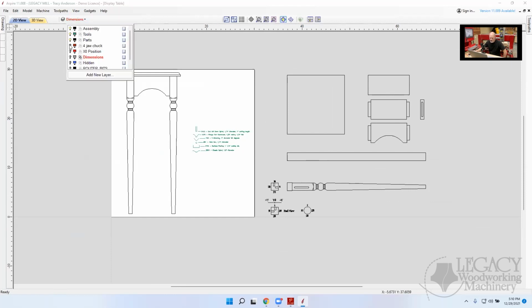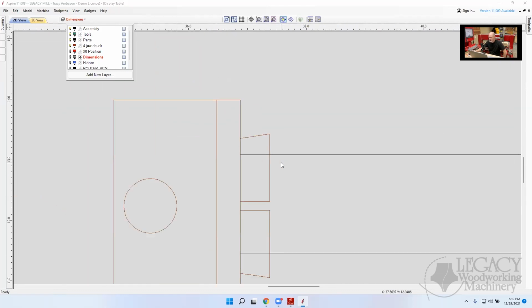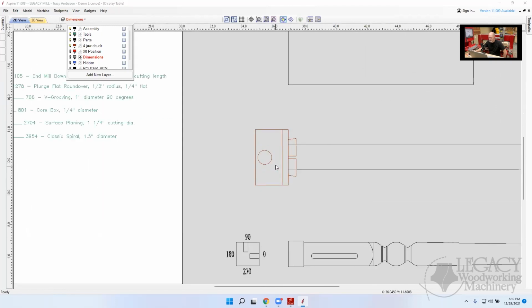Okay. And then I added, if you were going to put a 4-jaw chuck on it, that's what the 4-jaw chuck, this is the, I'm sorry, I got this mouse that's really overactive. Okay, this is the 4-jaw chuck. It's the Record Power SC3s. These are the dimensions. Yours might be different, but I measured and I can insert a 1/2 inch into the jaws. Okay, so I decided to set the x-axis 0, 1 inch from the end of the blank.